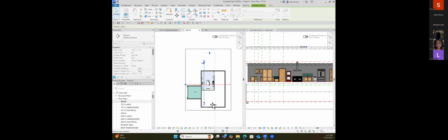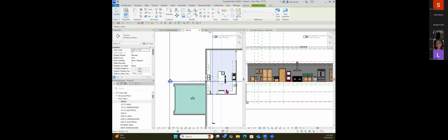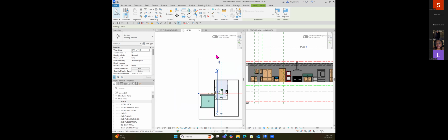So I'm going to say, don't go so deep. So now it won't show me anything on that side of this dashed line. That's the depth of field of my section. So when I go back to that section, I'm not confused. I don't have all that clutter in the background. And I can align that to here.